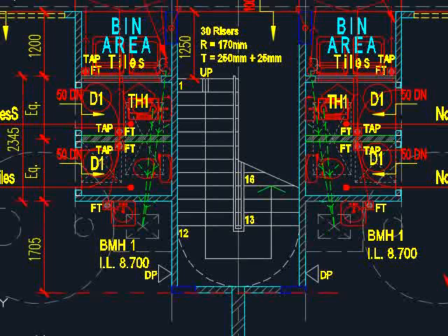If you see this part also, the architect also proposed the column. Most likely this is going to be another part of the aesthetic view. You can try to adopt this size. For a typical multi-story building, less than 3-story height, I believe the size proposed here is already more than enough. It is not necessary for you to increase the size of the column, since it's already indicated by the architect. Maybe you just adopt the size of the column.